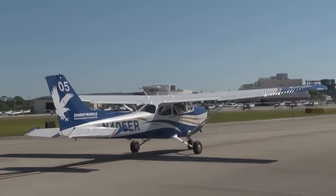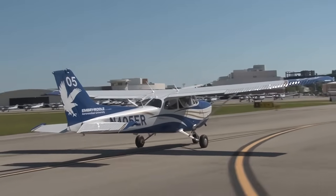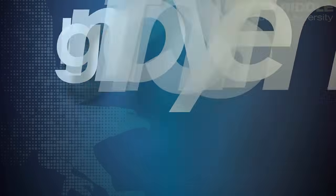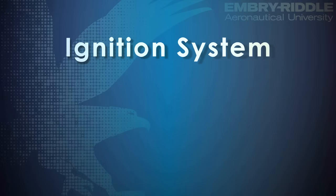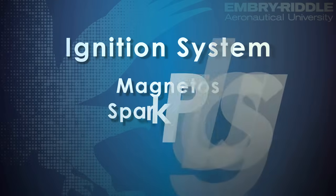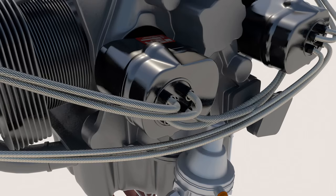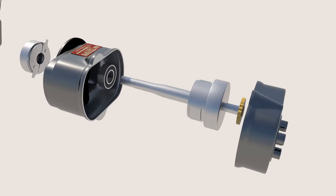Now that we've discussed how we get fuel and air into the cylinders, let's talk about how we get that mixture to ignite. The ignition system is what provides the spark to the mixture. The major components of the ignition system include the magnetos, the spark plugs, wires, and the ignition switch. Just as its name implies, a magneto consists of a rotating magnet that generates sparks of electricity.